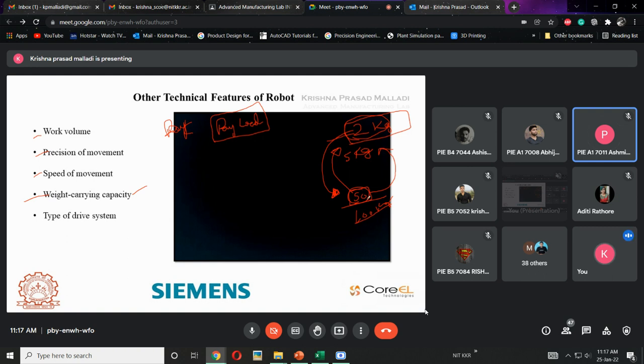Yes. See, this robot is designed for 50 kg. The robot is meant for heavy applications, but by using this heavy robot we are doing a small application, which is a 2 kg application. So the application can be performed, but at the same time we are not utilizing the robot properly. Because the robot has a 50 kg payload, the power capacity, the power, the facilities, all the things involved for the robot will always be more. Because of much more involvement of all these resources, the end application will be like this. So this is in no way useful to the industry.